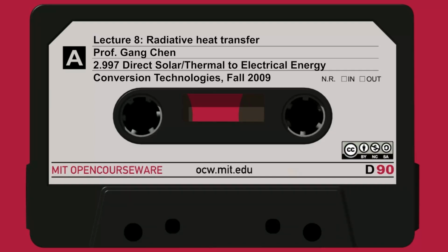And of course, I used this trick before: this area times the view factor is the same as the area on Earth times the view factor from Earth to the sun, so I can cancel the area. So it's independent of area here, and that's why I was doing the universal blackbody curve.